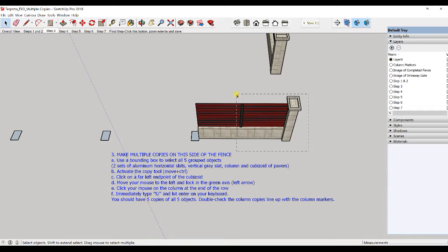So we just need a little piece from each grouping on our right to left crossing window. So I've got them all in my bounding box. I'm going to let go. I can see that all of them have been highlighted. Now, if you accidentally picked up part of the text, you can redo that. Or, remember, if you get too much, you can hold down the shift key and select or deselect, as it were, what you do not want. Don't forget that one. All right.